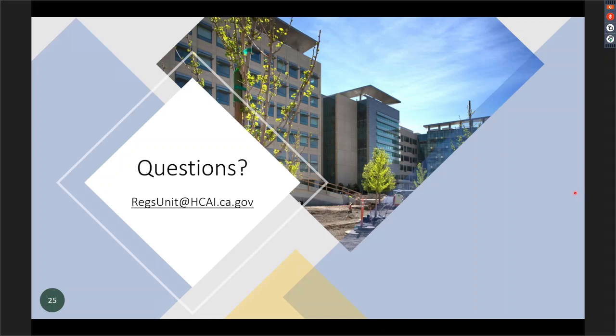Adding clarification, I used this earlier, adding a dimension that's not shown on the plan, but doesn't change the plan. It's just not clear where a wall is located or where a piece of equipment is located. So the contractor says, where is this located? You provide that dimension. Again, you did not change anything on the plans. You just clarified a location for the contractor. That does not require an NMA or an ACD. It's just an RFI and stays an RFI. Those are the two simple examples I've been using.